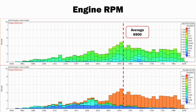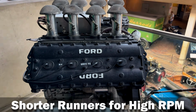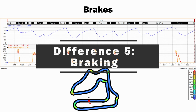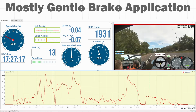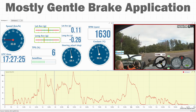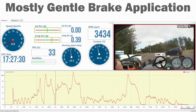Now there are some other implications around tuning. So if you are going to be running at a higher RPM, like a race car, you're generally going to want things like shorter runners to tune your peak torque at a much higher RPM than you would have on a road car. Now, if we're going faster and we're still hitting corners, that means our brakes are used in a very, very different way on a race car than they are on a road car. On a road car, we're generally applying our brakes very smoothly and building up some pressure, not just slamming them on and using the maximum amount of braking. Now, also, we're generally operating them infrequently. So that means our brake system is usually cold when we're applying the brakes.